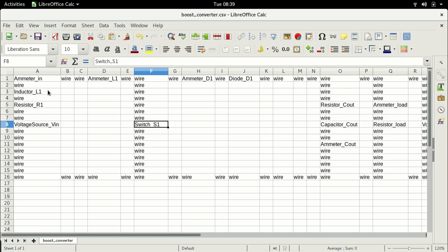When this inductor is discharging, there are now two sources that are feeding the output. It is the input voltage and the energy in the inductor. Both of them are now feeding the output. The result is the output voltage is going to be higher than the input voltage. We are now boosting up the output voltage above the input voltage. This now becomes a boost converter.